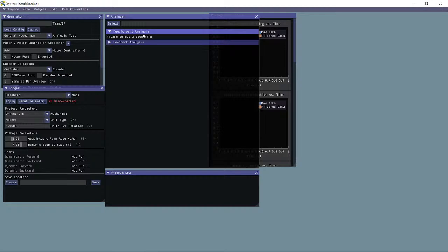I mean, we're talking about flywheels specifically. Will feed forward be enough to control them, or is there really any difference between using solely feed forward or implementing feed forward with PID? I'll cover more about feed forward and PID in a second. But if you already know about it, this feedback analysis section will give you PID gains to combine with feed forward. So it's pretty cheap to get the PID constants to add on top of feed forward, and then you just use a library to implement the algorithms for you, and you just use the numbers that are in here.